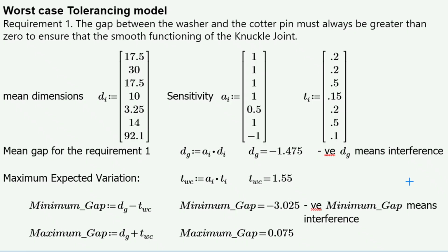You cannot assemble this part with this way of giving tolerance to this assembly. If we give only size tolerances, then you see what problems are going to come, or whatever tolerances we have given need to be optimized. And the maximum gap shows 0.075, 75 micron. So still it's going to be more difficult to assemble all the parts together.